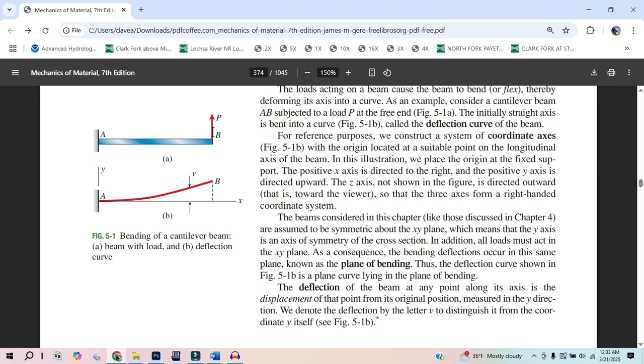No, I messed that up. I have a constant shear force. Yeah, this one we talked about. So our shear diagram, draw it in, is going to be a constant load. And is it going to be in the positive direction? No, check this out. So like here, taking this little thing, this load is going to cause it to rotate that way. So that direction is associated with negative shear.